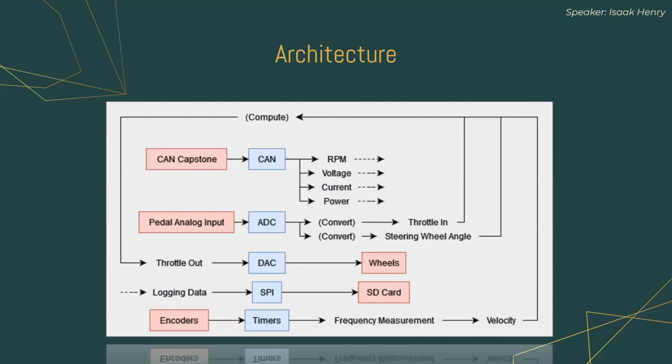We have also set up frameworks for more calculations by allowing data to flow from the CAN bus into the microcontroller, which can then be used for future calculations. We also set up the framework for SD logging through the SPI communication channel, which allows users to log any data they want through the SD interface.